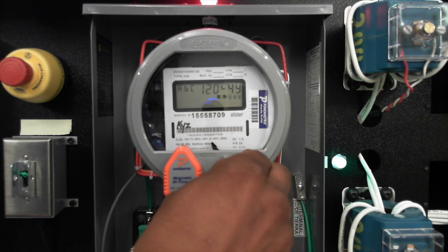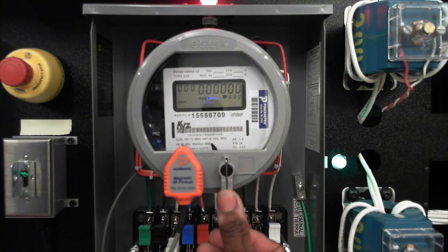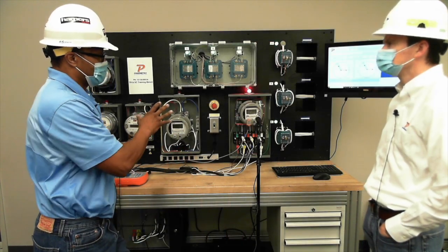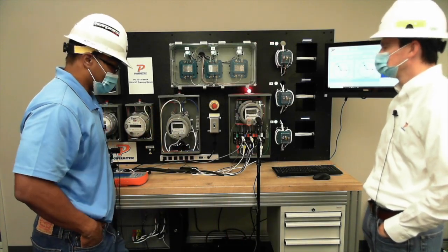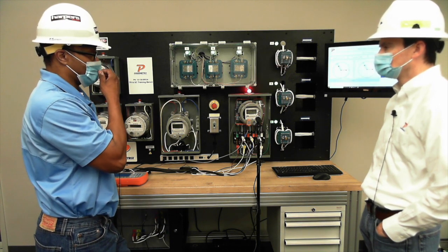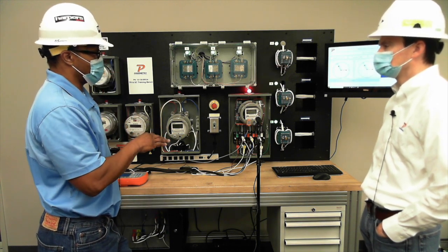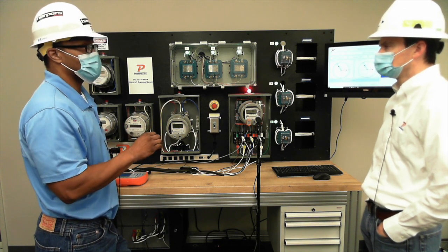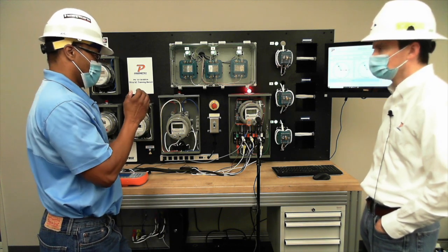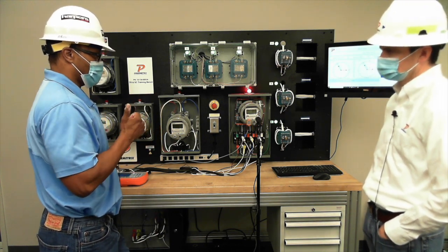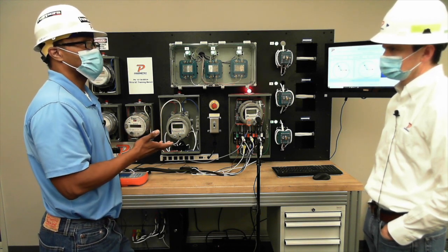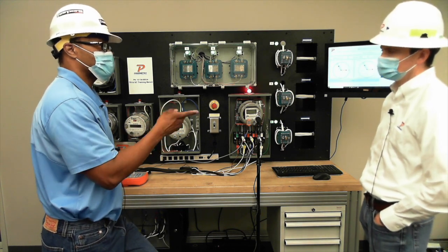That's another thing you can always do too. You just press that in and hit reset. Is that reset button standard on all meters? Yeah, but some of the meters nowadays you can read by phone, so you probably wouldn't have to do that. But it's still very important that you write down the kilowatt hours and the kW while you're there, which is your energy and power, just so you can document it and have that information. So when you go back to the shop and they say the meter's not calculating at all, you know what it was when you were there. Right, so it helps the back bill.